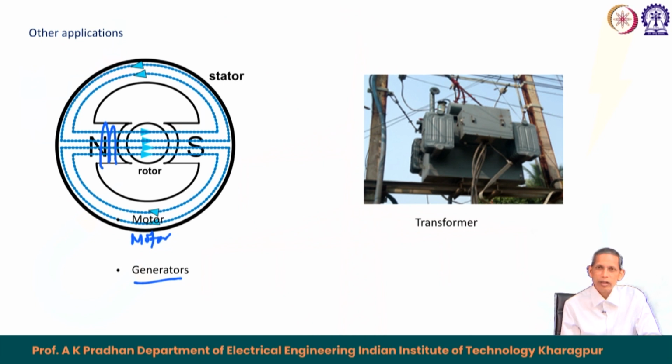So, in a magnetic field, a rotating conductor develops a voltage, and that voltage can be connected to the outer wall for electricity supply. So that is about the generator cases. Typically in large stations, in thermal and hydro stations, we have large generators called alternators, and those use electromagnets to produce field or flux, and from there the rotating conductors give us the voltage.